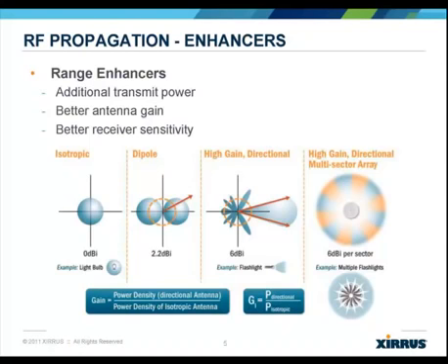Most AP vendors integrate one or two radios and omnidirectional antennas in their APs. As a result, all clients within the footprint connect to one of these two radios. On the other hand, Xeris uses 2, 4, 8, 12, or 16 radios and directional antennas. Because each antenna has its own directionally focused sector, we're able to get at least twice the distance and 4 times the coverage of traditional omnidirectional antennas.